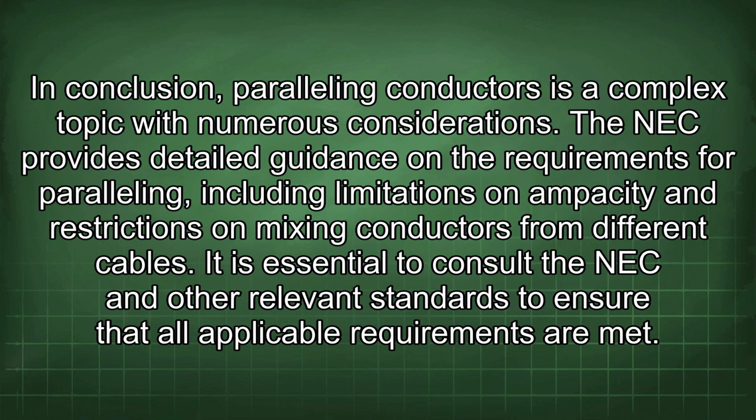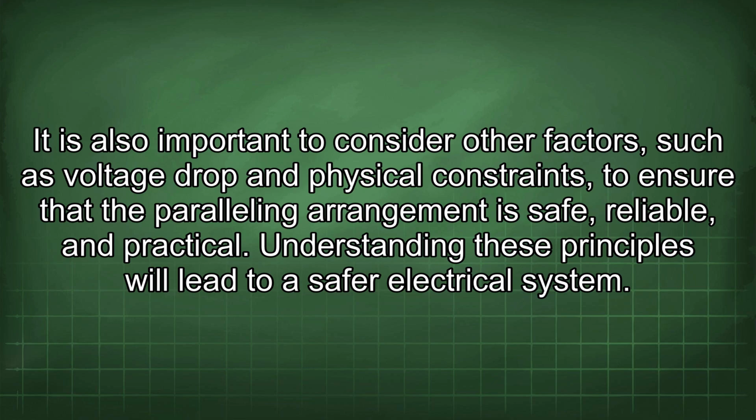In conclusion, paralleling conductors is a complex topic with numerous considerations. The NEC provides detailed guidance on the requirements for paralleling, including limitations on ampacity and restrictions on mixing conductors from different cables. It is essential to consult the NEC and other relevant standards to ensure that all applicable requirements are met. It is also important to consider other factors, such as voltage drop and physical constraints, to ensure that the paralleling arrangement is safe, reliable, and practical. Understanding these principles will lead to a safer electrical system.